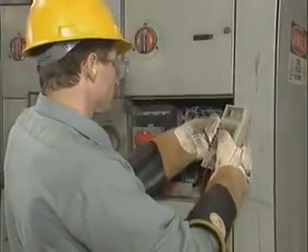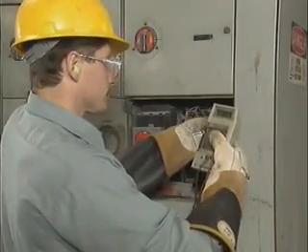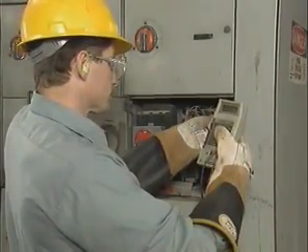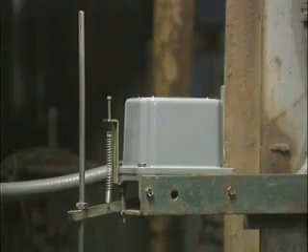While you're testing, pay special attention to any replaced or repaired components to ensure that they are operating correctly. Also, while you're testing, you may need to make adjustments to the controller and reset devices that require resetting. For example, after a pressure switch or a float switch is repaired or replaced, you may need to set the operating levels for the switch.